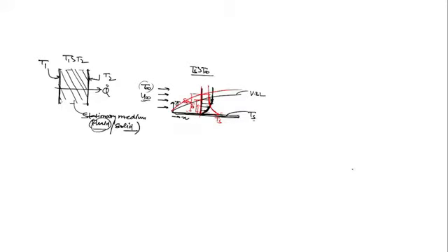So the thermal boundary layer thickness, how can I define it? As we are moving in the y direction, the temperature decreases, and once it reaches 99% of the upstream temperature, that thickness is called the thermal boundary layer thickness. Clear? Yes or no? So the black one indicates that u is a function of y, and the red indicates T as a function of y, the temperature variation as a function of y.